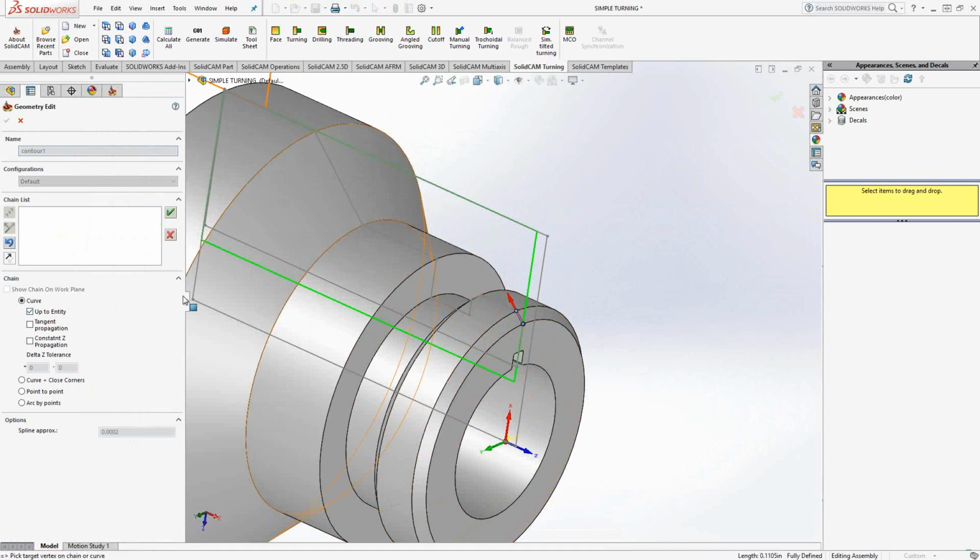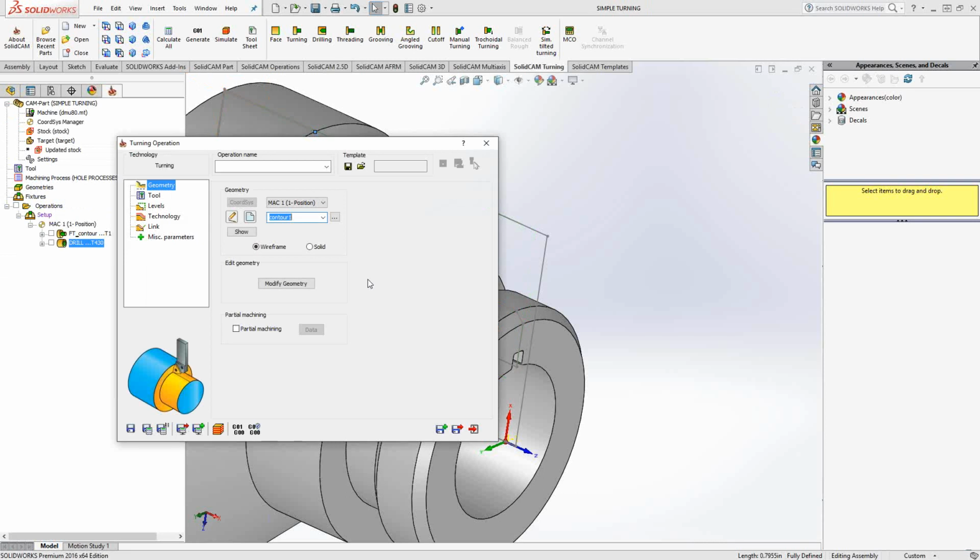In this case, what I'm going to do is choose the last entity in this toolpath, right here. Basically, this is where I'm going to take this toolpath right to the chamfer. If I click on that, it finds the connection between that last entity that I selected and the one that I just selected. So basically, it completes the chain for me. So click the green check mark. It's orange now, so that is what we're going to machine out of the green contour.